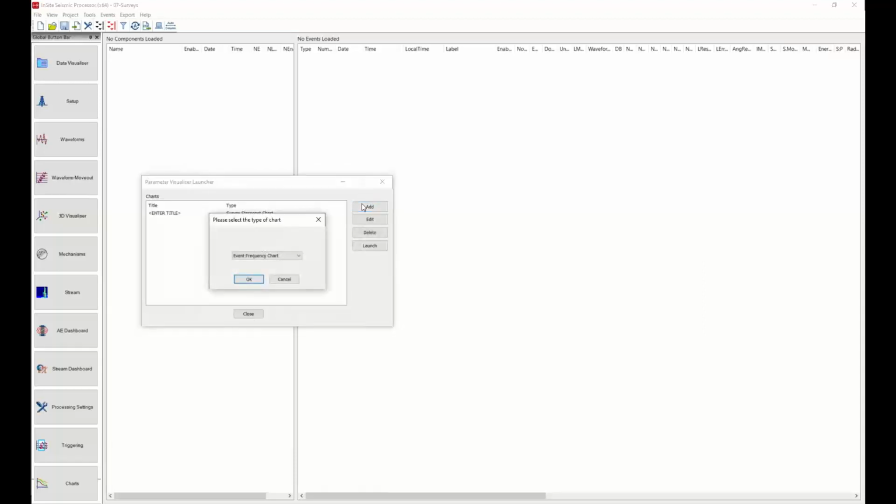And I'm going to add another chart, which is the velocity survey chart. This one displays the velocity measured across different ray paths. So let's display the P wave velocity. We can either calculate it from the peak or from cross-correlating with a reference survey. We need to look at different ray paths, and we define them here.